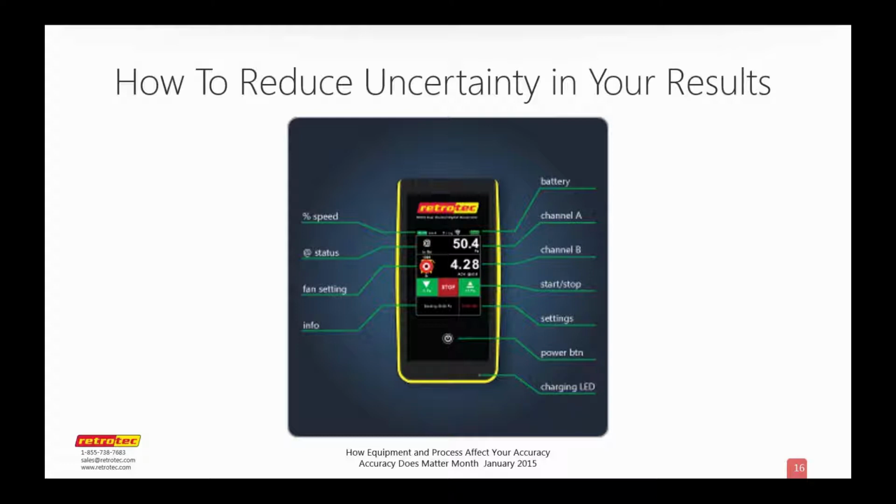We've already talked about checking your fan monthly, and like Colin said, I think the most important thing is, yes, there are many state and local codes and standards about how often you have to have them calibrated, but if you're not given specific limitations, then it's best just to check them regularly: your gauge weekly, your fan monthly, and decide whether or not they need it.